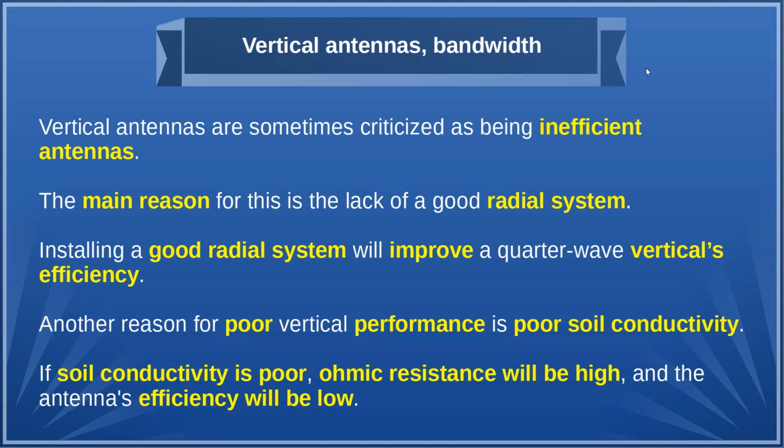Anyway, if you've got bad soil, you've got a high ohmic resistance. But one thing, if you do QRP work, like at Kelly Park, put your antenna right in the water, it works real good. And we'll be at Manteco, which is on Indian River, that works real good. And that's salty, right? Oh, yeah. That's where you could use a vertical dipole right at the water's edge. They're very effective right at the water's edge, but at your house, they're not.